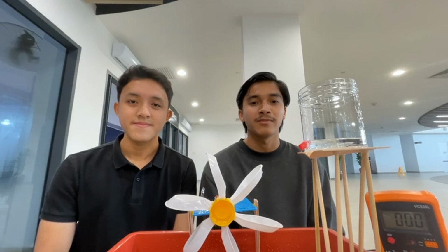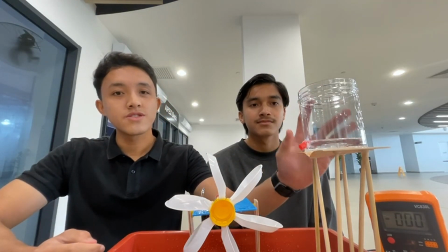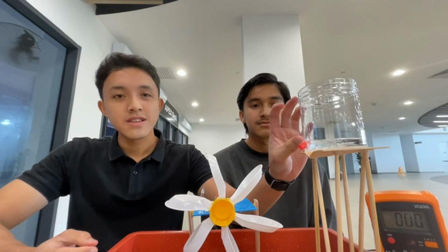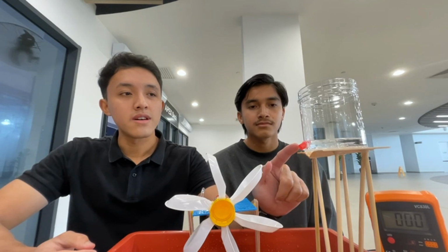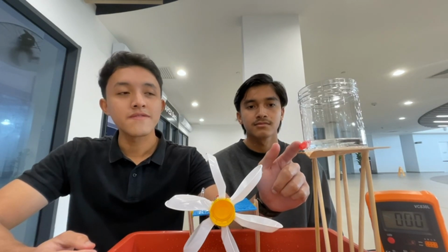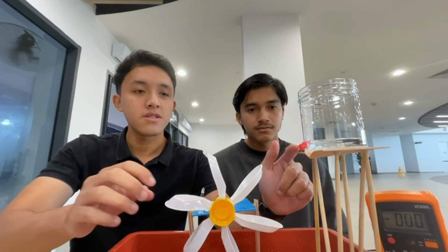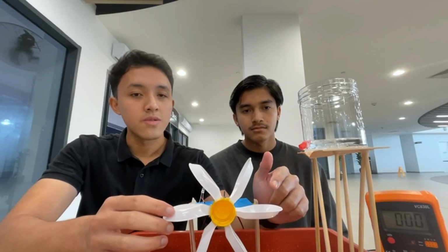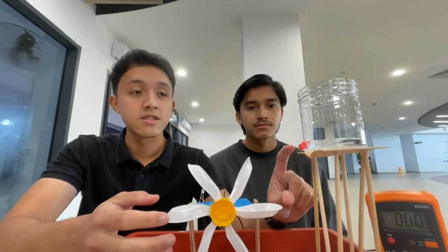So this will be explained by Haikal. Okay, so as you can see, when we pour water into this tank, which is our water reservoir, the height difference in the water tank produces a pressure. So the outlet velocity of the water is calculated by the square root of 2gh. This velocity is the kinetic energy, and as the water goes down and touches the turbine, there's also a height difference producing additional kinetic energy.